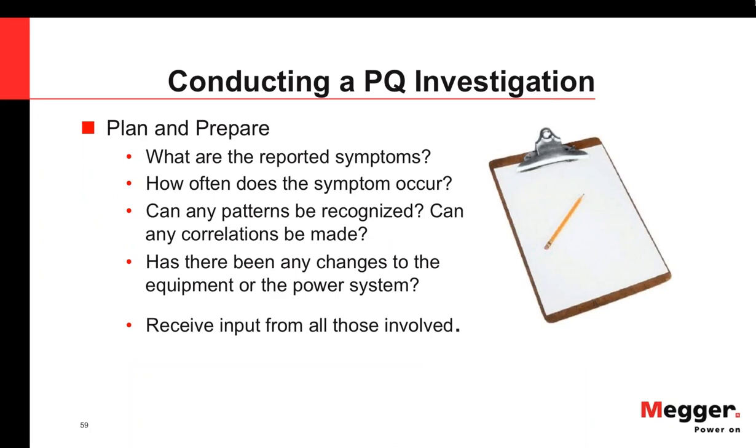So when you're looking at rapid voltage change, it's a smaller change than a sag, and steady states are required. So this is what differentiates it from an actual sag or a swell, which is a momentary event. Rapid voltage changes can happen continuously and be quite small.